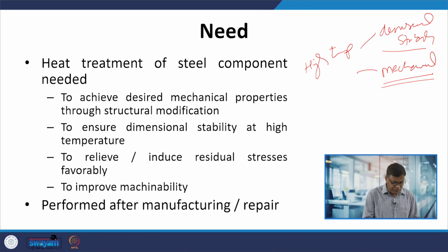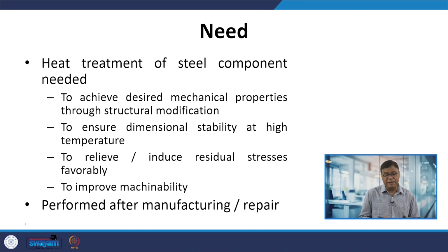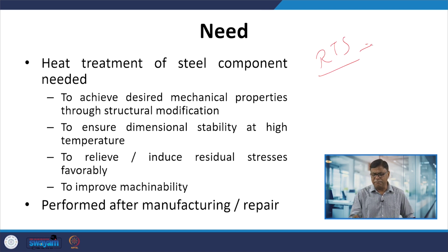Then we know that during manufacturing processes like casting, forming and welding, a lot of residual stresses are induced, and these residual stresses tend to adversely affect the mechanical performance. If residual tensile stresses develop, they compromise the tensile load carrying capacity and the fatigue resistance under tensile loading.